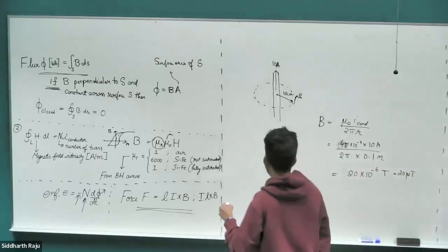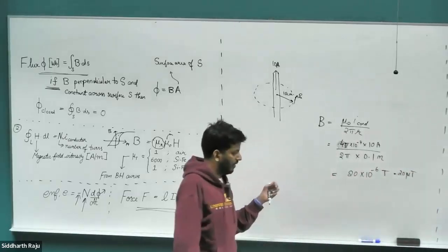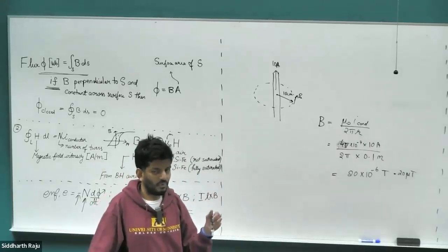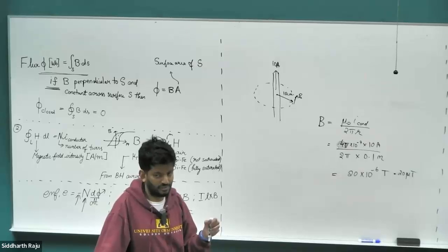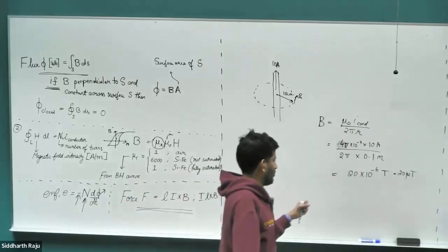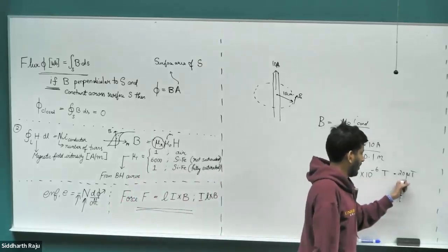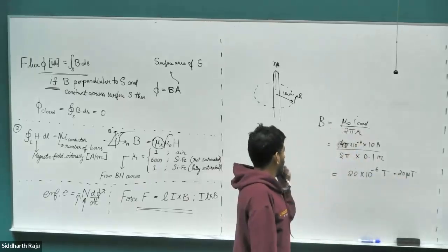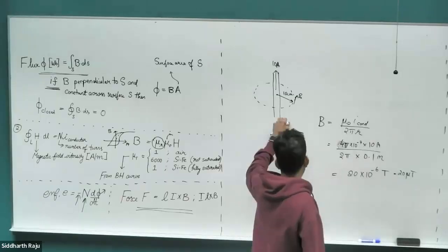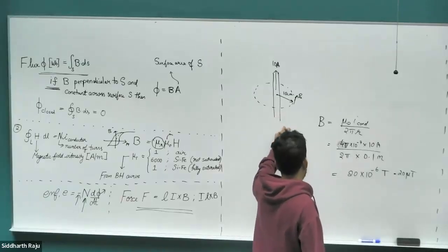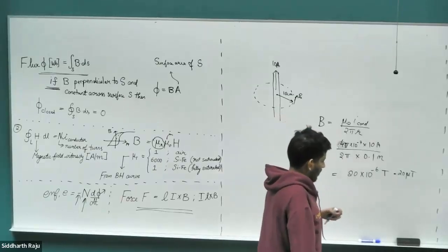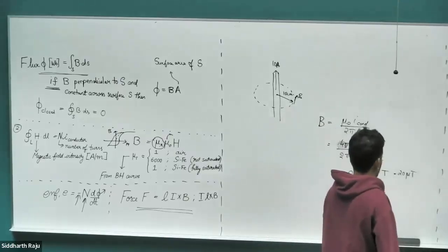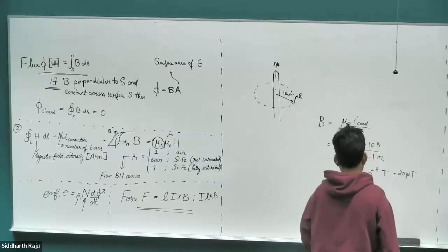This is very small because in a motor, typically, if you look at the air gap, you would want a magnetic field of around somewhere between 0.5 to 1.2-ish Tesla. So we are 10 to the power minus 6, less than 10 to the power minus 5 lower than the intended value that we want to get to. So air gap has this very bad property where it's not a ferromagnetic material, so it doesn't amplify the magnetic field. So we typically want to put this thing inside some kind of magnetic material so that the magnetic field can be much, much greater.